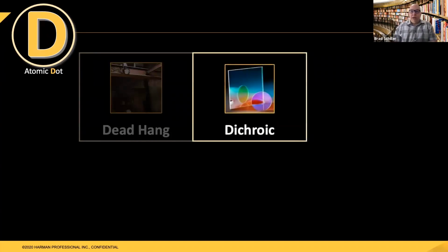We also use dichroics throughout lighting fixtures. Dichroic is basically a really great system where you take glass and you coat it in a big chamber. A laser will hit a certain chemical, heat it up, and that chemical will go up and rise onto the glass, and the glass will be coated. Once the glass is coated, now it becomes like a filter where only certain wavelengths of light will pass through that piece of glass. And that allows you to have a piece of glass that, for instance, takes white light and allows only magenta wavelengths to pass through.